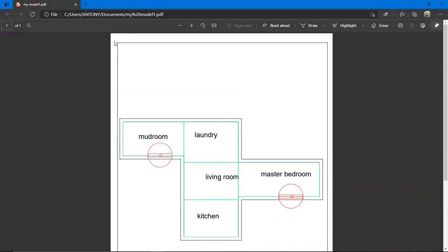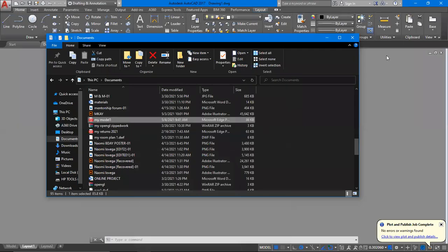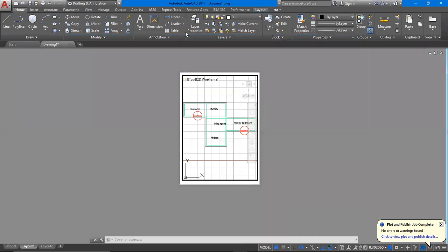But you can see it comes with the viewport. Sometimes you don't need this viewport because it was not part of your drawing. You can remove that viewport, by the way, by just creating a layer. I can come here to my layer properties. Let me go back to the model.